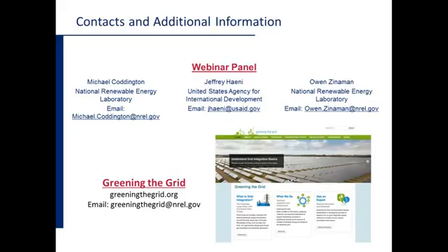Also, because Germany employed a proper buy all, sell all feed-in tariff, they haven't really had fixed cost recovery issues that I kind of reviewed in the same way that you would in a net metering or a net billing scheme. So now, at the same time, that doesn't mean that there aren't revenue issues. They have a huge amount of rooftop PV on their grid that perhaps was not envisioned 20 or 30 years ago when many of their larger conventional generators were invested in.